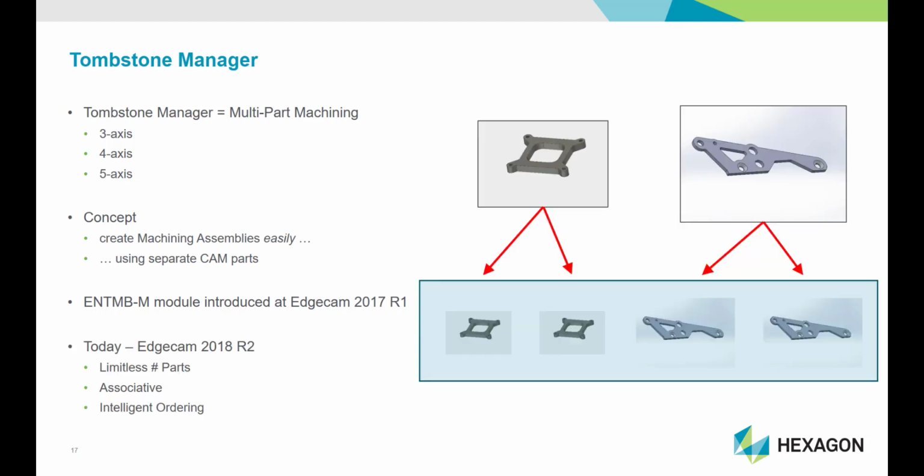We're finding that some customers using the insert component, then merge sequence, and then rationalize commands to build a software workflow for their multi-part setups have not considered the Tombstone Manager. It's a very efficient software option. We'd like to encourage you to think about multi-part machining when you see information about Tombstone Manager.